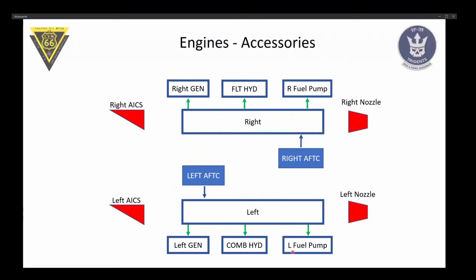By the way, this is not the pump that's in the combustion chamber. This is basically an additional pump that pre-pressurizes fuel before it gets into the combustion chamber fuel pump. So you have basically two pumps. The one that takes fuel from the fuel lines out of the tank and then sends it to the fuel control pump, which then actually pumps fuel into the combustion chamber.